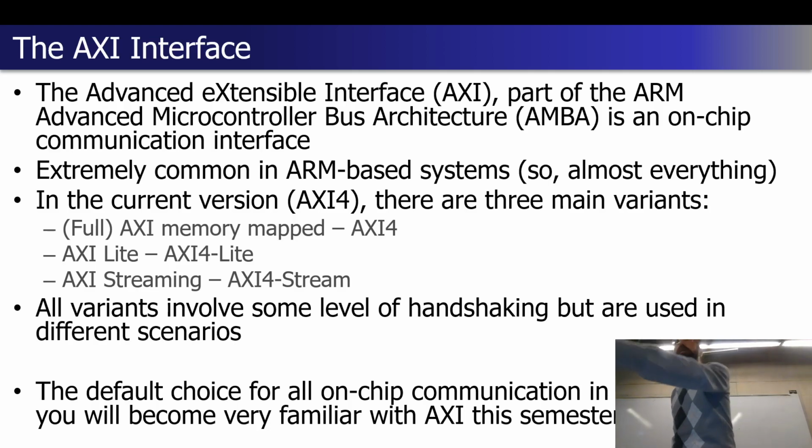We also talked on Thursday about FIFO interfaces, how they don't entirely solve this issue of communicating between a sender and a receiver, but they provide you that buffer. They use, as a trade-off, an amount of memory to store intermediate sent values so that, assuming you take some care to monitor whether or not the FIFO buffer is either full or empty, you can also resolve those handshaking and communication challenges.